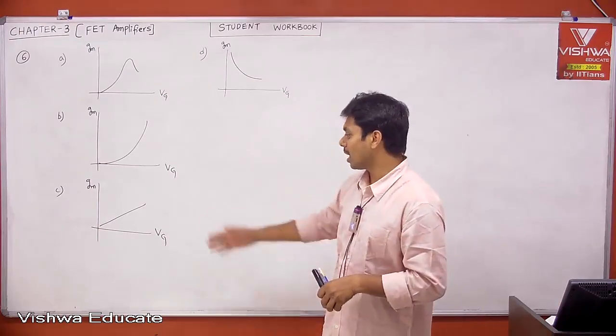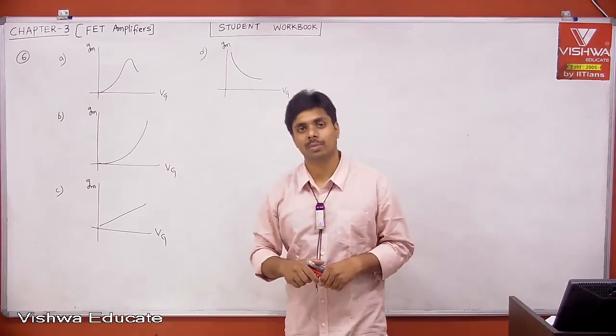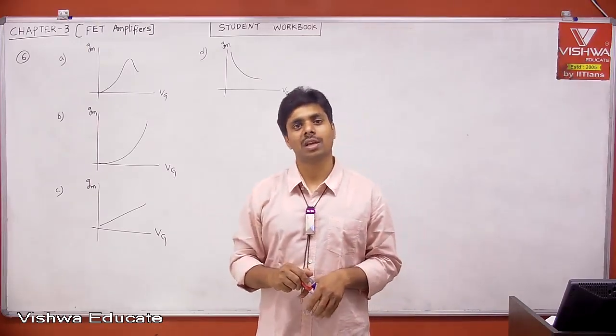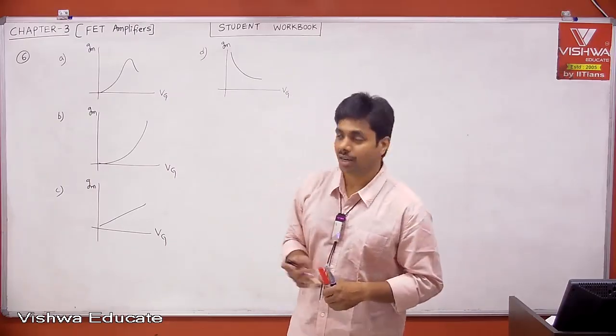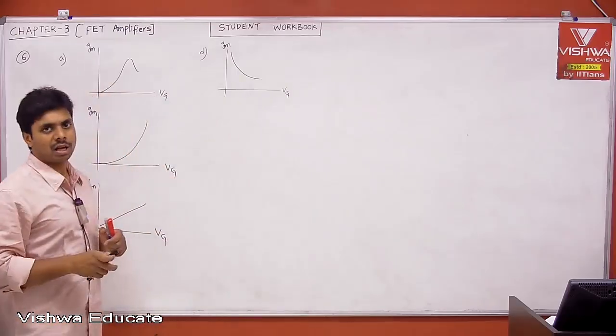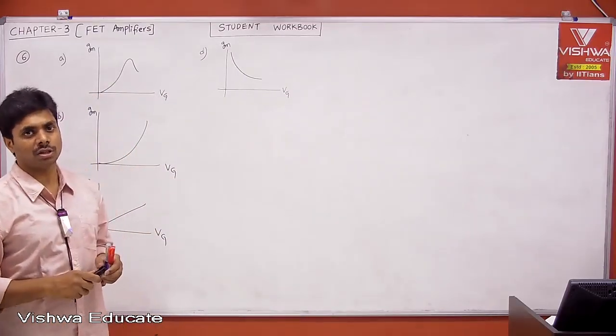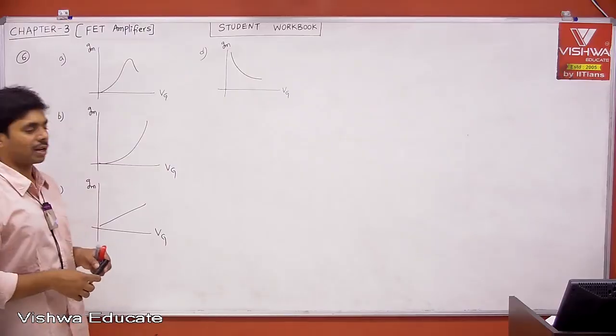Therefore, don't say that answer C is correct, because that is true with respect to voltage bias, that too when the transistor is in saturation. When the transistor is in linear region, all these plots we had seen are not valid, because we did them only for the saturation region. Now we need to derive once again.